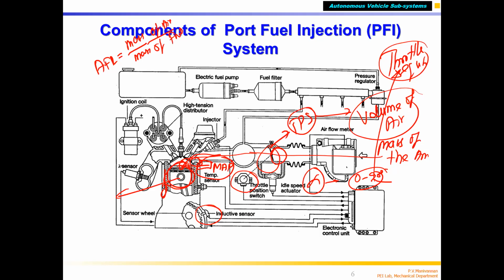You are not measuring air. Air fuel ratio, you are doing all using maps. In between values, temperature, all these things, you cannot give infinite number of maps, correct? So creating maps, as I told you, maybe 20, 30 different conditions, you store it, but it is not accurate. So the N alpha method is not very accurate, but it is simple. If it is a simple control and less cost, and you are not too worried about very accurate control, then you can use the N alpha method for air fuel ratio control.